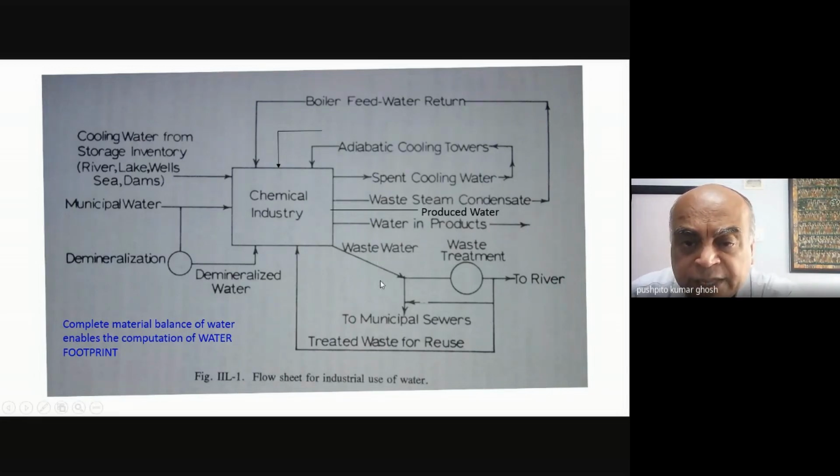But if that's not the case, then in many industries, they have to dilute their wastewater with fresh water, make it comply with the discharge norms, and then discharge it. Which would mean that again I am consuming water for the purpose of discharge of the wastewater, not to speak of the fact that some water has obviously not gone in for good use. Otherwise, I could have reduced the requirement of water in the plant.